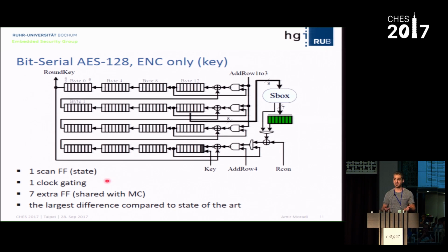Here we perform the key scheduling at the same time as the subbytes and the add round key. Meaning that in the 128 clock cycles in which the add round key and subbytes of the state are performed, we also apply the key scheduling. The point here is that we need the S-boxes for the state only in one clock cycle out of 8, and then we have the other 7 clock cycles per byte to use the S-boxes for the key scheduling. It's pretty efficient.